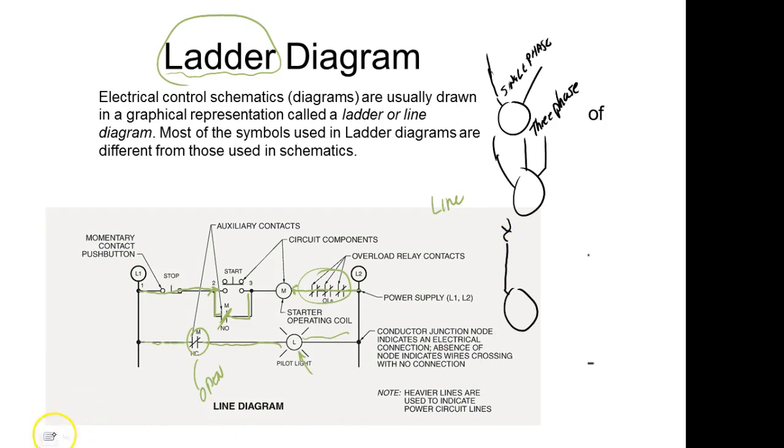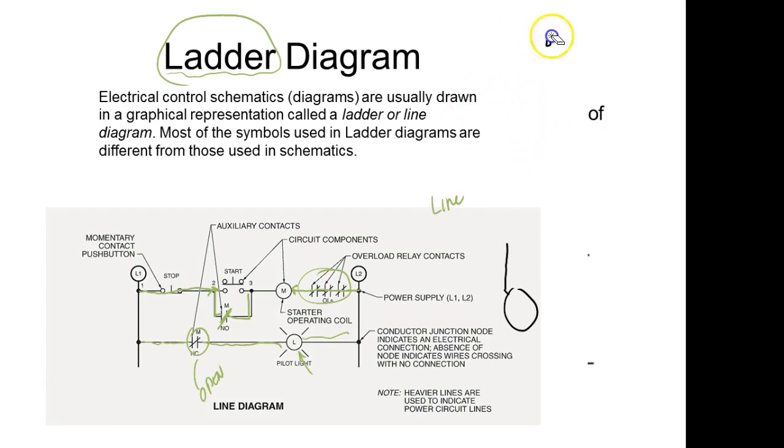Oh, that's not a symbol for a fuse, guys. That's a symbol for an overload. So up here somewhere, we might have a big old disconnect where we can disconnect power from the system. And somewhere up the line, we're probably going to have a fuse. Industry still uses a lot of fuses, and why is that? Yeah, they're cheap.